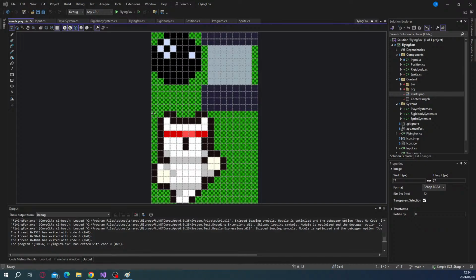I want to use this particular texture. So if you look here at the bottom, this little thing, watch that. So it will be 0, 12, that is the position of the top left corner of our texture. And the other position, maximum position, is 11, 25.